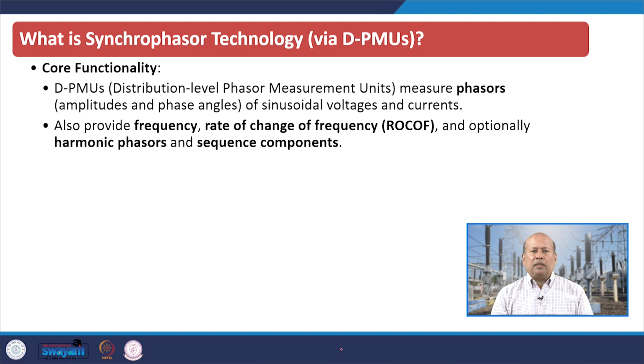Now, what is synchrophasor technology? That's very, very important. Core functionality: a distribution level phasor measurement unit measures phasors, that is amplitude and phase angles of sinusoidal voltages and currents. It also provides frequency, rate of change of frequency, that is ROCOF, and optionally harmonic phasors and sequence components.